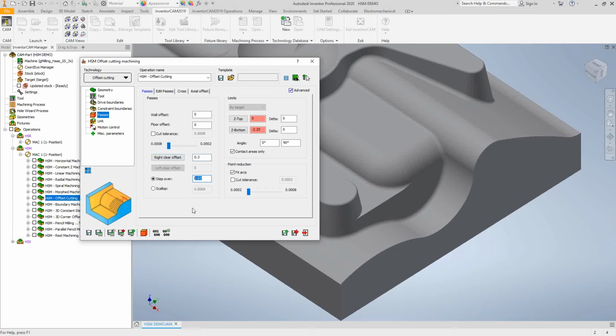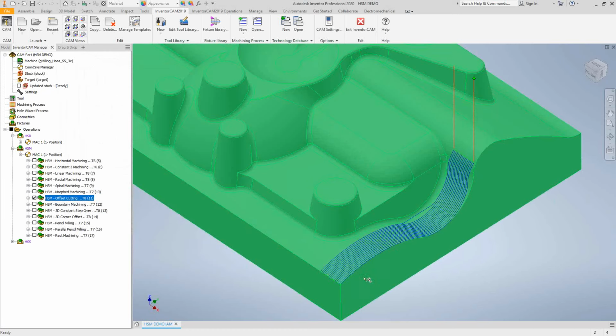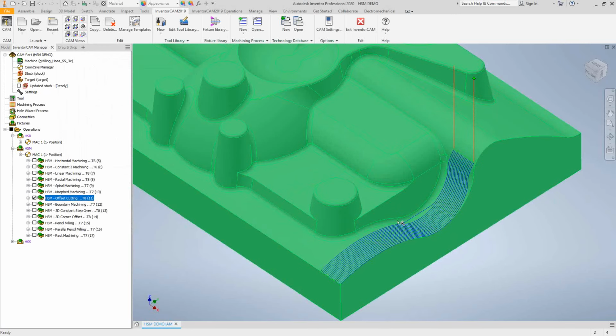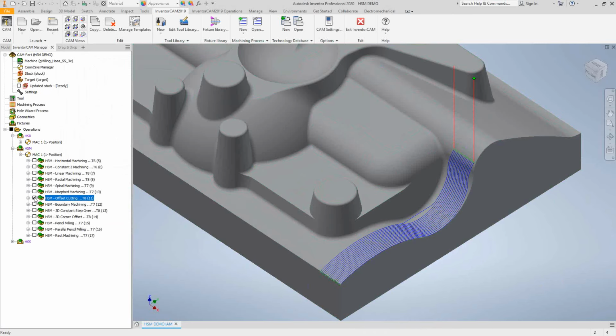So this is a similar toolpath to also what we saw in video 6 in the profile, where we're doing a clear offset, and it's similar to the video 12 HSS parallel to curve in that we're giving it a curve to follow. So this is one toolpath that you can consider does all in one. And all you're really doing here is just choosing one edge, and as long as the features on that solid match that edge, you'll get a nice finish. And again, this is another good example of limiting the travel of the tool, because I probably don't want to follow this as I go along. It's going to get a different looking toolpath as we go along. Probably not going to like it too much.